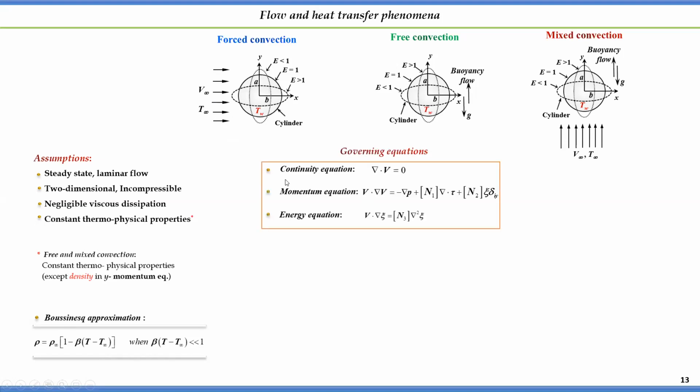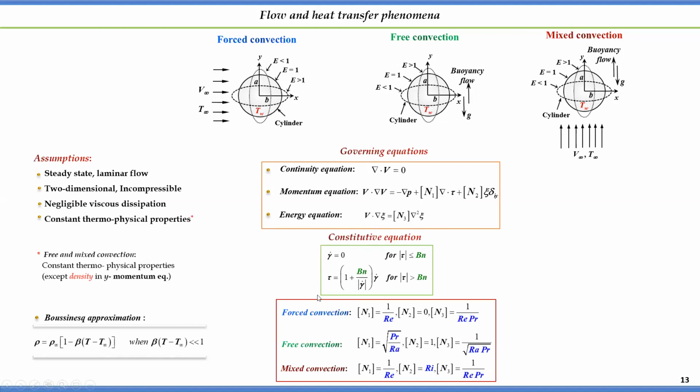Let me come to the governing equations. These are the governing equations after imposing all these assumptions, in simplified form, and these equations are in non-dimensional form. The constitutive equation for Bingham plastic we are going to plug into the momentum equation, and this constitutive equation is also in non-dimensional form. According to the different phenomena, forced, free, and mixed, these constants differ.